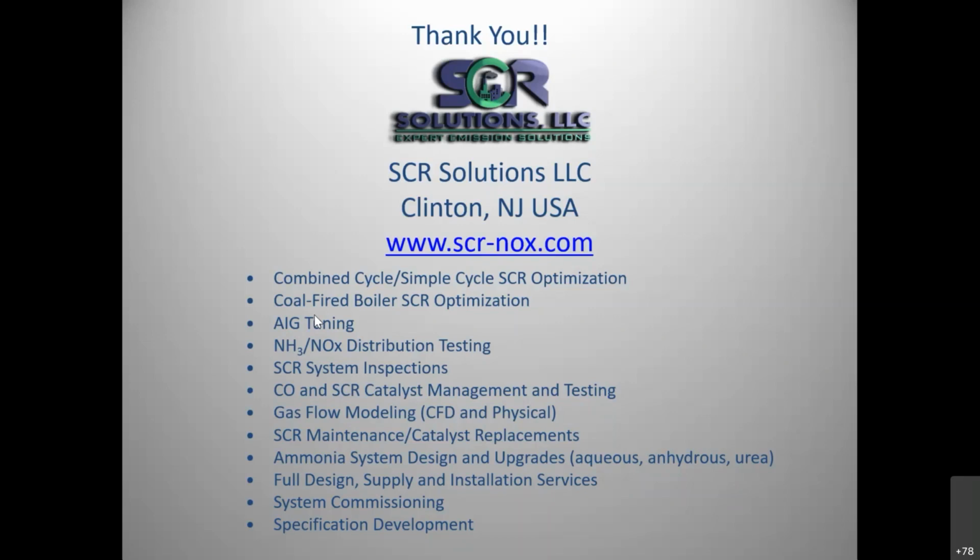Yeah, doing this method for measuring your overall ammonia slip, we've done this countless times where the stack ammonia slip measurement was reading something. We went in there and we measured 50 data points. We're in the stack, they're measuring 1 or 2, and we're seeing numbers that are either higher or lower. But we've got 50 data points, they've got 1 or 2, so we're going to rely on our numbers because we're using a very reliable instrument, the FTIR.